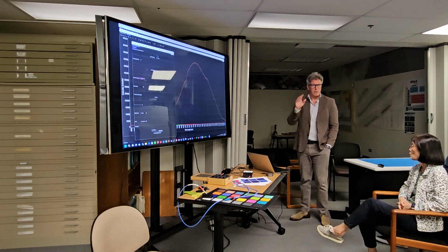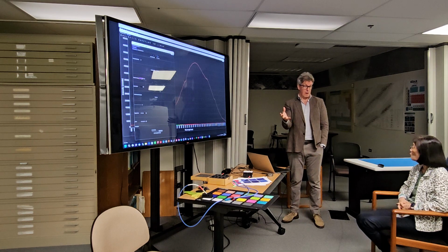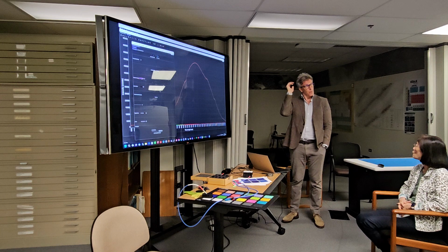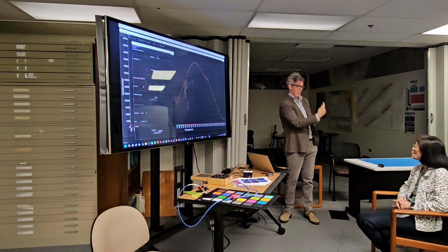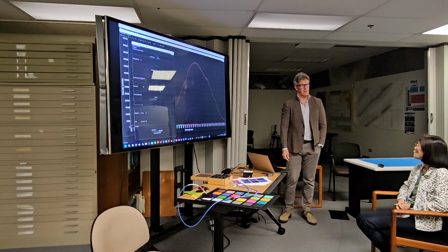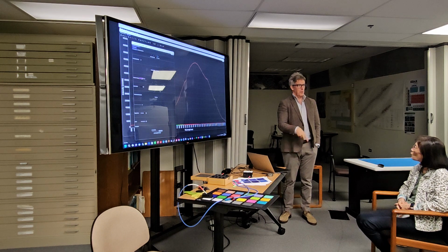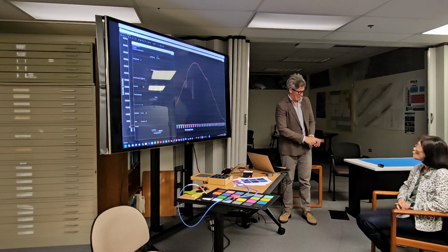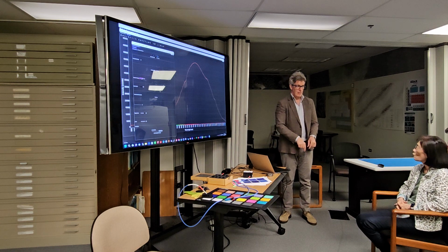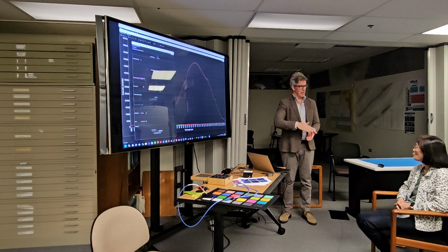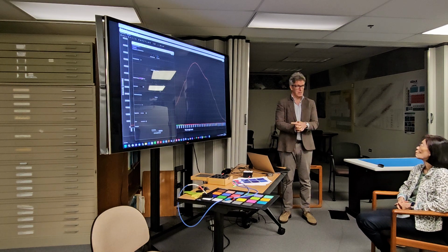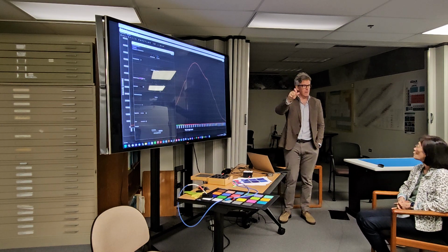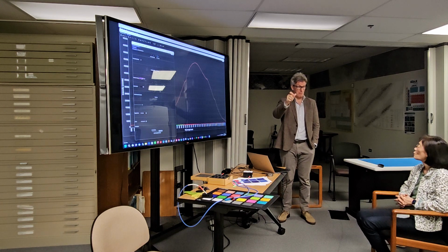Okay, so when you're designing spacecraft, and we'll show you this, one thing we're going to work out in the future is we're going to take light photons from the sun, cascade them down onto the surface of the planet, take a target, and work out how many get reflected back. Based on the orbital velocity of the satellite, we're going to work out how much time we have available to make measurements from that patch of ground and that patch of ground and that patch of ground. We're then going to work out the maximum integration time we have available, and that's the parameter we're going to tune in this model to make sure we don't saturate whilst maintaining signal. Right, so integration time is the single knob that a space instrument designer can turn with relatively little cost.